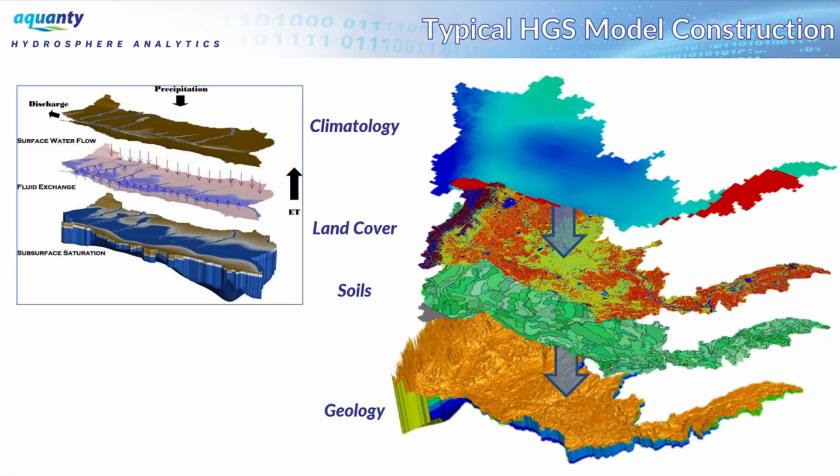So typically in HGS, we're going to be running subsurface flow, surface flow, and often evapotranspiration. And what that means is when you go into defining material properties and parameters, you need to come prepared with a conceptual model, like what we see here, which delineates the spatial distribution of different soil types or hydrostratigraphic zones, different superficial soil types, different land cover classifications, or potentially crop type information and how that impacts evapotranspiration.